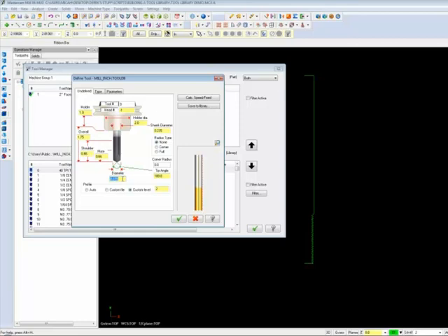So as the XYZ feed rates are active, we need that Z retraction to raise, assuming we're thread milling from bottom to top. So at one full revolution of that thread diameter, the tool needs to raise in the Z direction by exactly the pitch. But drawing those teeth on the screen would not affect your G-code output, but it absolutely would affect your verification so that you can see this hole actually being milled on the screen while you're verifying. So hopefully we've answered that.